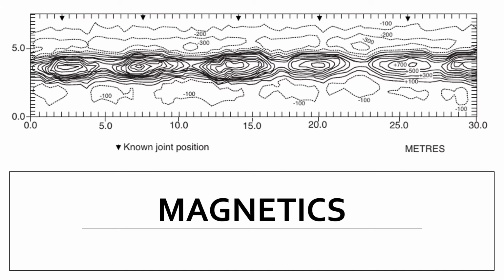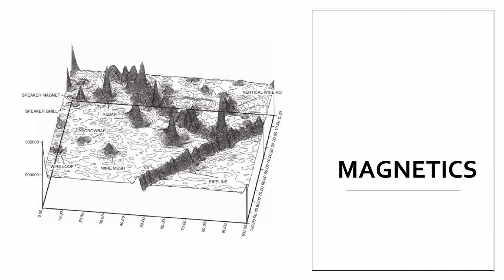All right, so this is a 2D model of the magnetic response of the subsurface, and there are known metal pipes. And what we are seeing here is we are registering a large magnetic intensity where the metal pipes are known to be located. Okay. This is another example in a landfill.